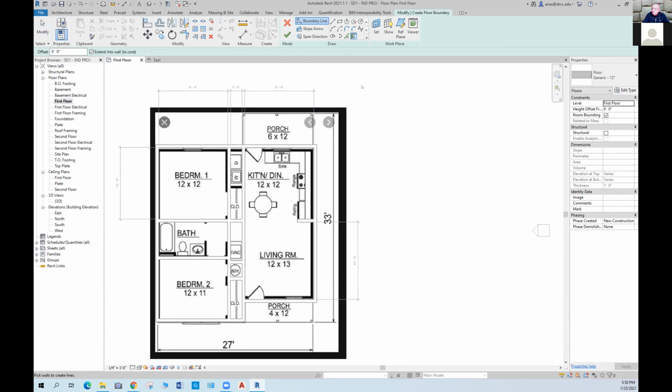And for the floor, I enter in this space called the sketch mode because I am allowed now to sketch the shape of the floor. I'm going to select the line tool, make sure the floor is generic, and I am going to lay out this floor by tracing this line, this pink line outside of the walls.